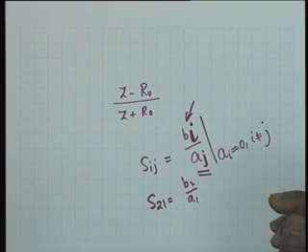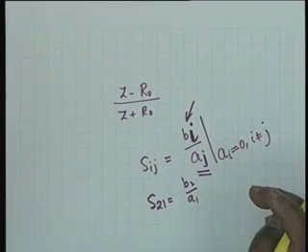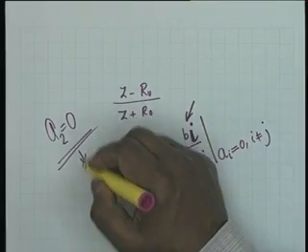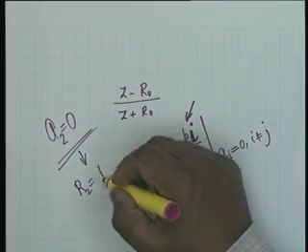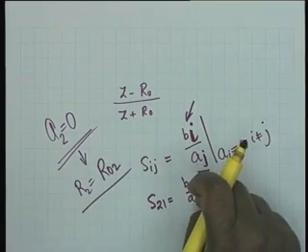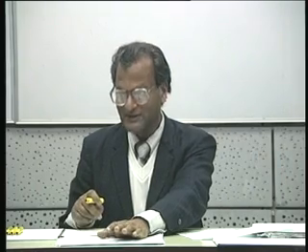If the reference impedance is taken equal to the terminating resistance. You shouldn't forget so quickly. A2 equal to 0. What was the interpretation? R2 was equal to R02. So it was a choice. And therefore, right from this definition, without going into that example, you should have been able to say that scattering parameters may or may not exist. But if they exist at high frequencies, it is a boon. The description becomes very, very simple. We close at this point.